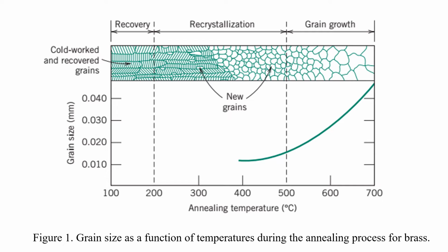The mechanical properties at room temperature of a fine-grained metal are usually superior to those of a coarse-grained one. To reduce the grain size, the refinement may be accomplished by plastically deforming the material, then subjecting it to a recrystallization heat treatment.